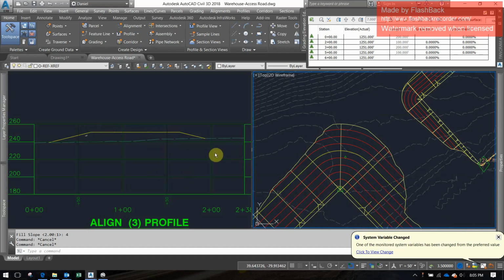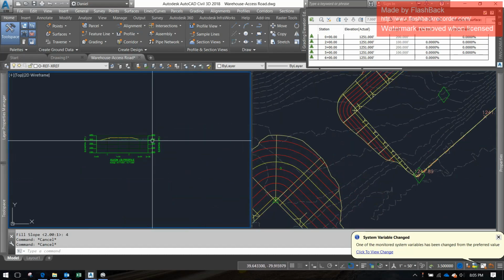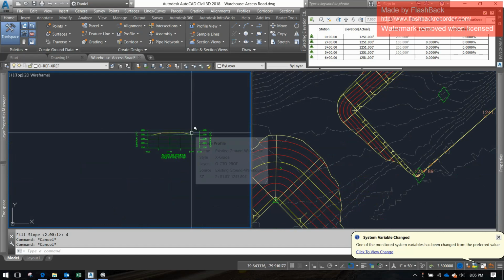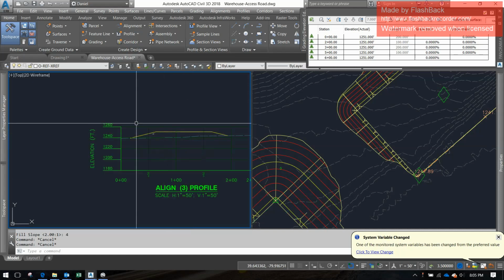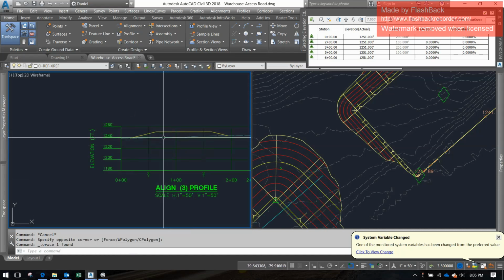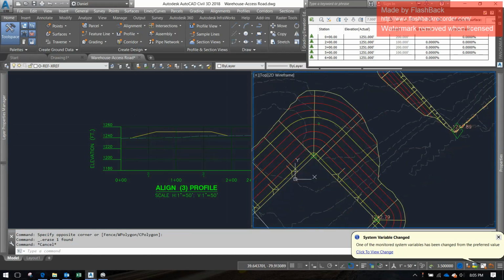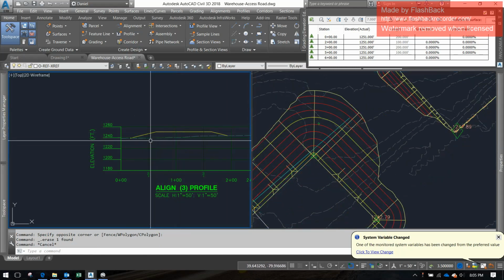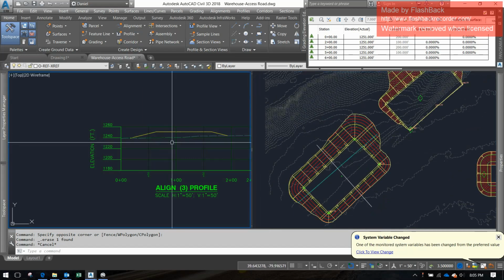And you've got to think about it from the standpoint of the angle of repose of an object. I think a 2-to-1 slope is equivalent to 50% grade, which is roughly equivalent to, I think, 30-some degrees, like 35 degrees or something like that. I think a typical angle of repose for a soil type is about 30 degrees. So if you have a slope that's shallower than the angle of repose of your soil, it's likely going to be stable. But that's not a guarantee. It's just kind of a best practice.